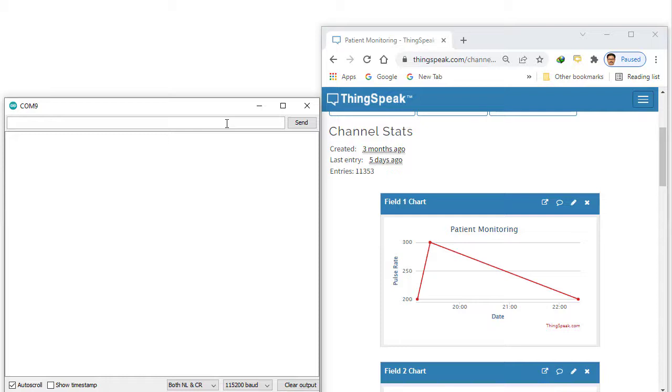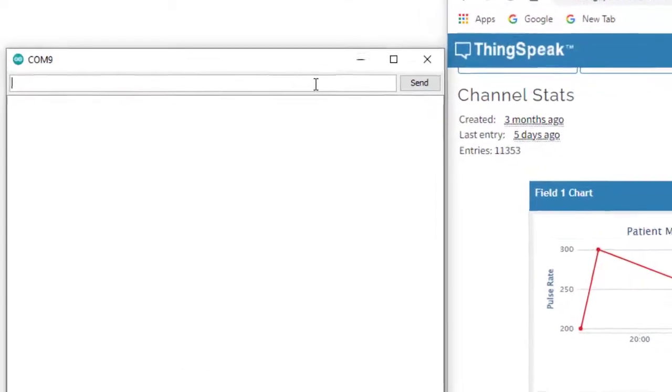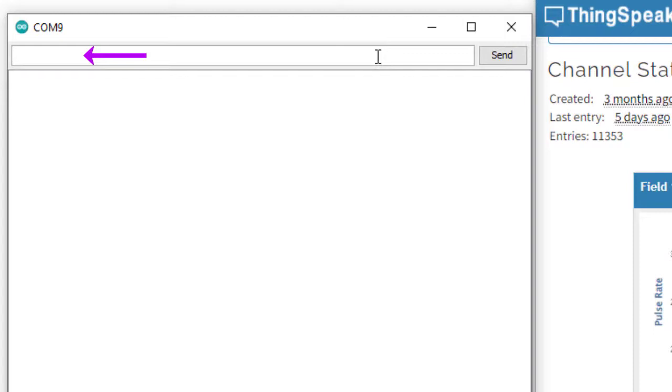First I am showing for single channel connection, and I will explain how is the response. For setting single channel connection, the command is AT+CIPMUX=0. Next I need to make a TCP connection with thingspeak.com with port 80. As this is a single connection, we will use no link ID, and the command is AT+CIPSTART= type of connection, which is TCP, comma, domain name or IP address of server.